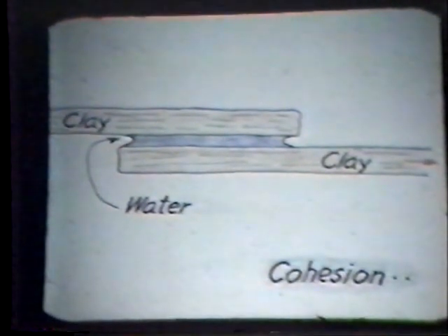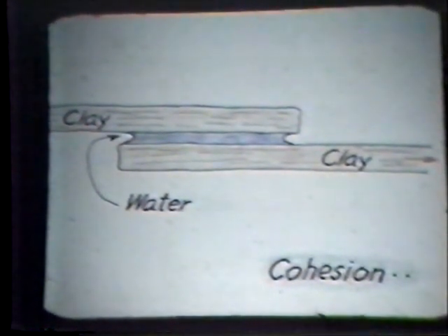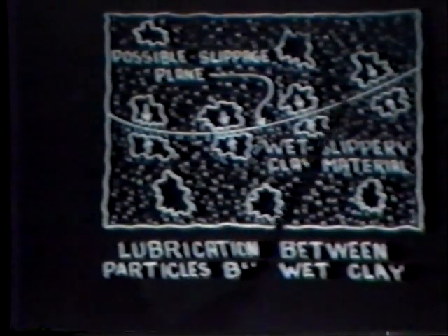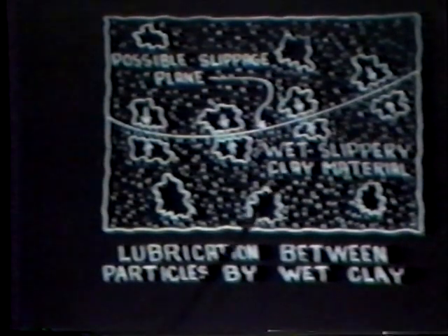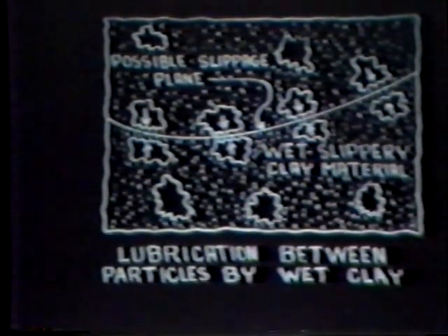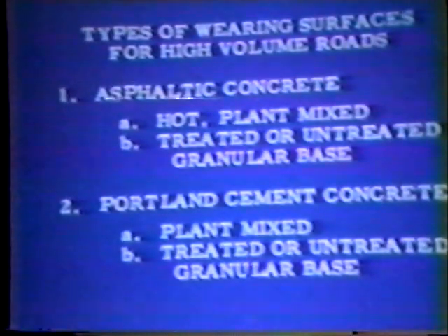And the reason for that is so as it does get moist, we won't have this problem of smooth, slippery grains sliding on one another. Because if you do, you wind up creating a much lower strength on this sliding surface, and as it gets wet, it becomes slippery, and the particles will slide by one another much more easily.